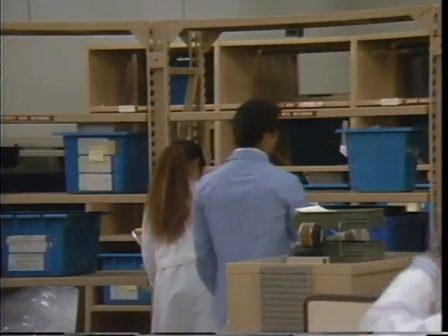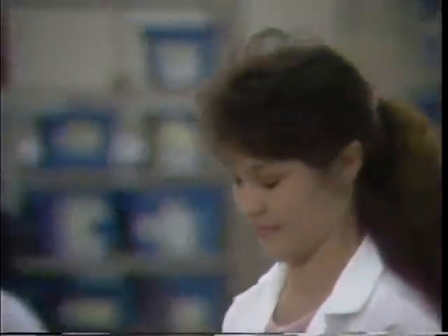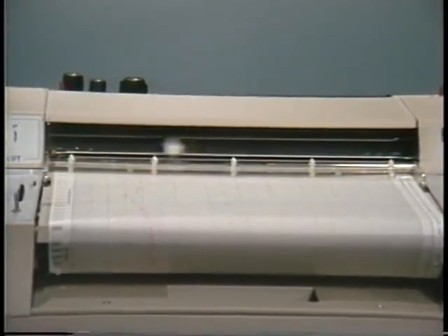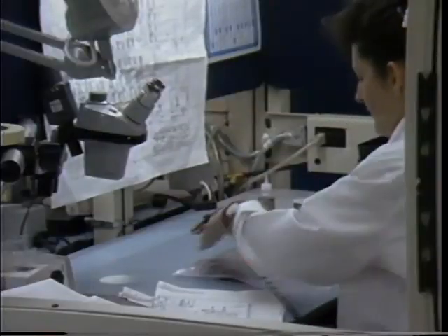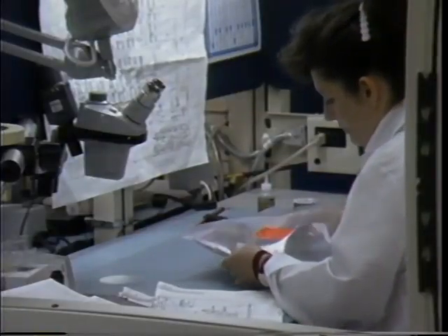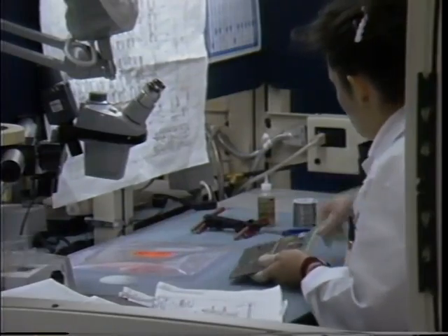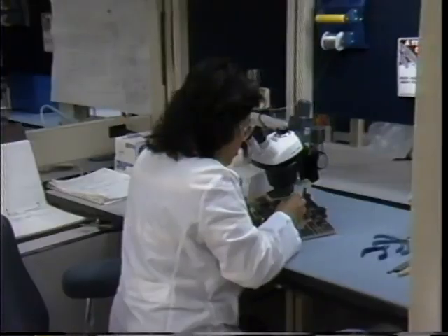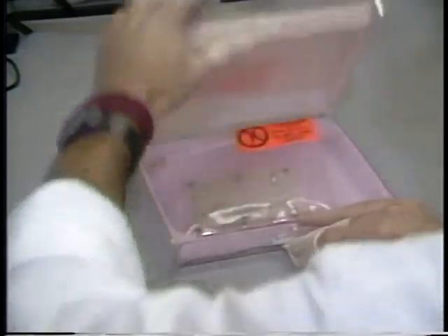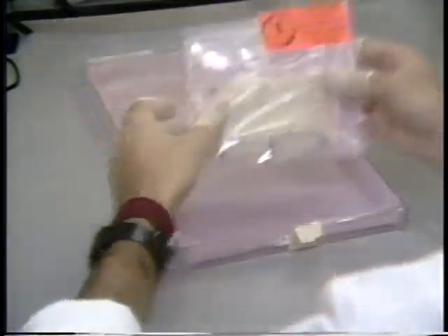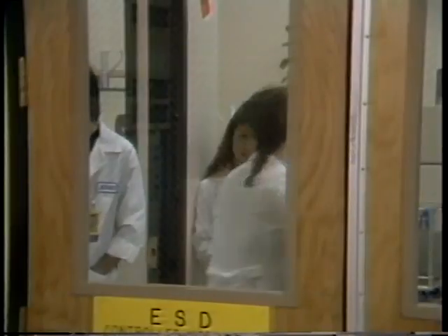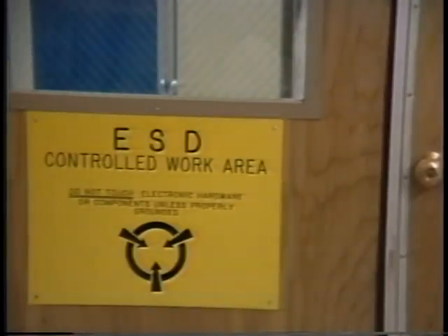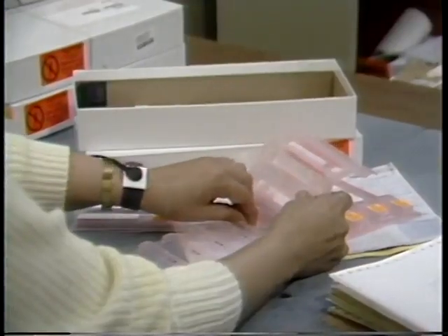The most common way that ESD is delivered to a sensitive component is by the human body. Earlier in the workstation example, we saw how the human body can generate voltage. When this voltage is discharged through an electronic component, it can damage or even destroy the component. The fact is that every type of component has a different sensitivity. Each one goes through many hands until its final use, so treat all sensitive components with the proper ESD control procedures. It's easy to see how critical ESD control is in preventing damage to sensitive devices.